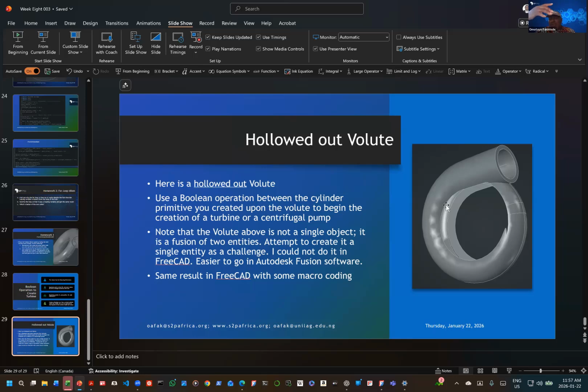So one is the opposite of the other. The compressor does the opposite of what a turbine does. In the compressor, you put in energy and it moves a fluid. In the turbine, you put in a moving fluid and it gives you energy out. But the design of the elements is essentially the same. They just work in the opposite direction. One takes a static fluid and sends it on a velocity. The other takes the velocity of a moving fluid and uses it to get the energy out, which can be used for generating electricity.